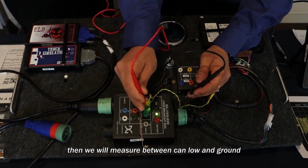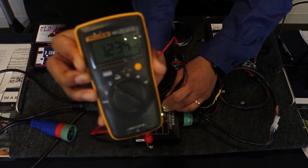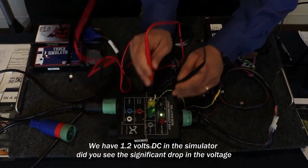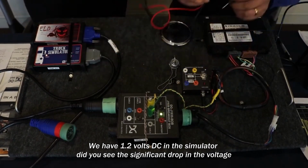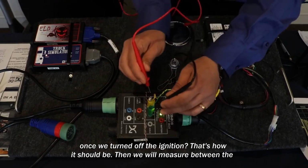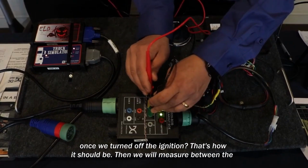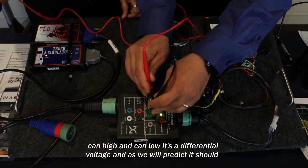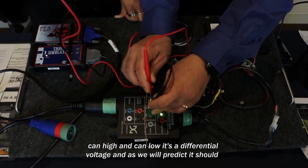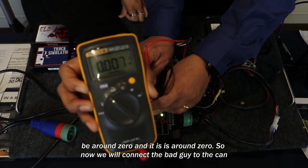Then we will measure between CAN low and the ground. We have 1.2 volts DC in the simulator. Did you see the significant drop in the voltage once we turned off the ignition? That's how it should be. Then we will measure between CAN high and CAN low. It's the differential voltage, and as we predicted, it should be around zero, and it is around zero.